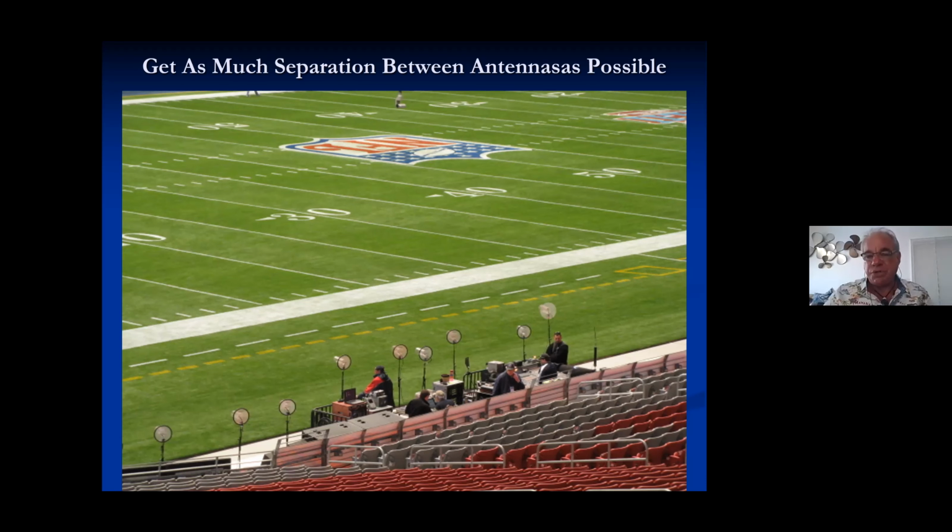Again, I'm trying to give you the tools and the fundamentals, and then you have to take these and process them into your own jobs, your own scenario. So we had, luckily this year, probably the last year that we had this much real estate on the side of the field. And Stephen was doing the comms, put the comm antennas, transmits to your left side of your screen. And then the wireless microphones more to the right, and then in-ears way over to the right. So we kept the mics away from the in-ear transmits. Very important to keep some distance between transmitter antennas and receiver antennas.